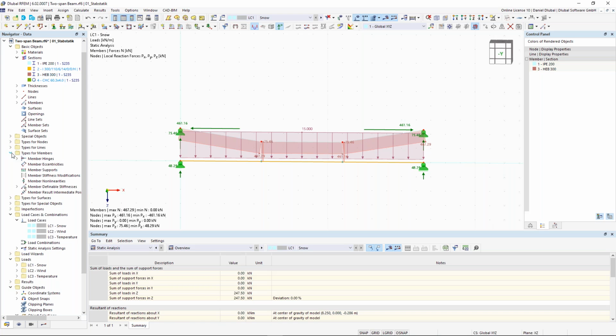Yeah. In general, everything is possible in the 3D FEA program. The question is how you consider it, also regarding the calculation. My approach would be creating the existing structure, of course, and then assigning the new member with some couplings.